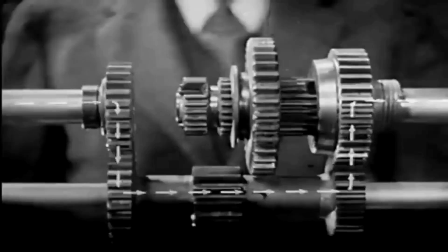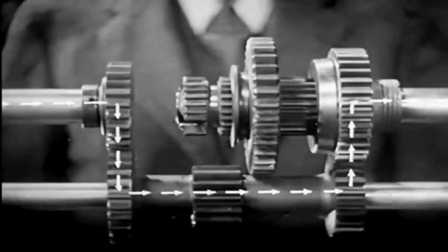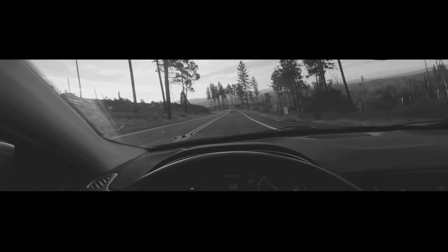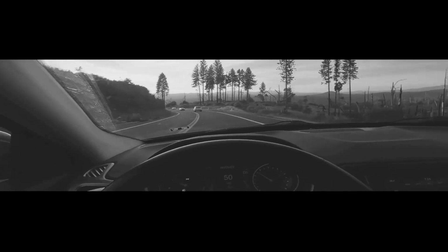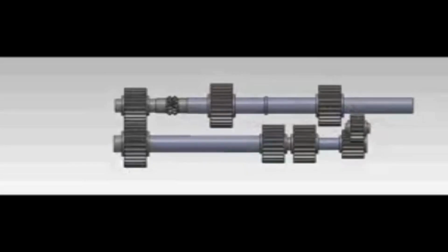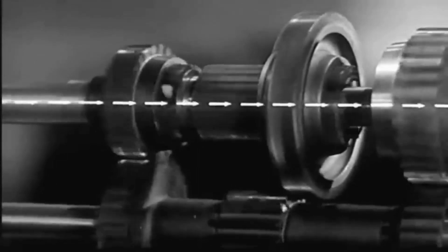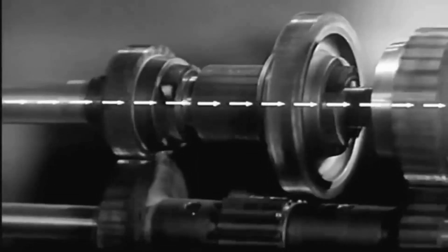In second gear, a medium-sized main shaft gear engages with the corresponding layshaft gear. This delivers moderate torque and a higher speed compared to first gear. In direct drive, the clutch shaft is rigidly connected to the main shaft through a dog clutch. This configuration allows both shafts to rotate at the same speed, ensuring maximum transmission efficiency with minimal power loss, as no gear meshing occurs during power transfer.